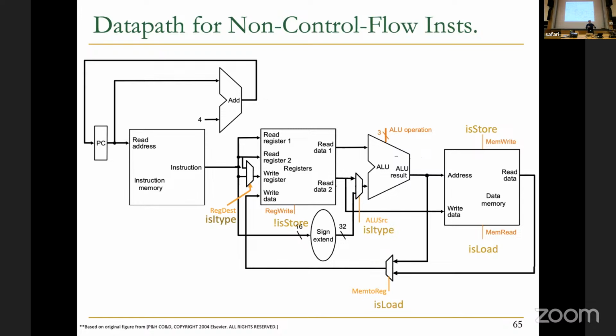If you want to add another instruction, you need to provide the data path elements as well as the control signals to execute it. Does that make sense? Okay. So this is how you build a data path, basically. This is how you execute the instructions: add the data path elements that are needed and the control signals that are needed. And this is one way of building the data path. Okay, any questions so far? Otherwise, I'm going to jump into other things.